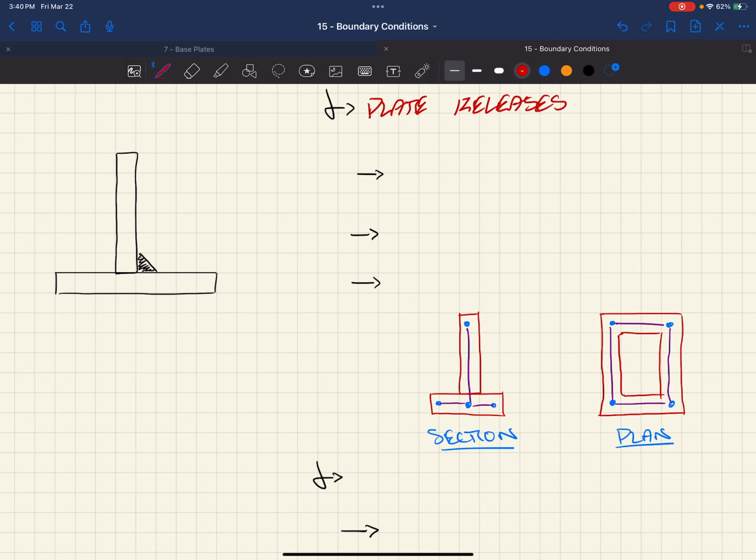If we look at concrete masonry units, CMU, it would be big retaining walls or shear walls for buildings. In wood, big elements would also be shear walls, which we would model as a plate representing the OSB or plywood sheathing on the outside of a building. That would typically be our shear wall material. And then you would have to make sure you're modeling the stiffness appropriately to get the right results. So if we look at some of these, shear walls are common.